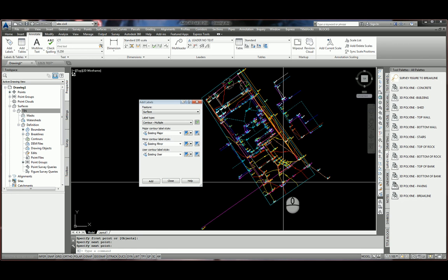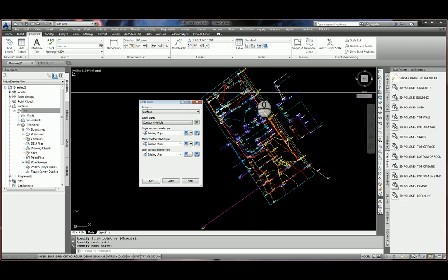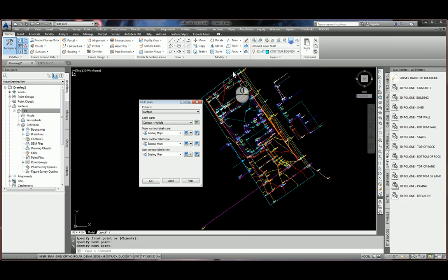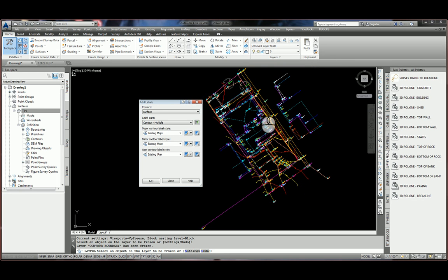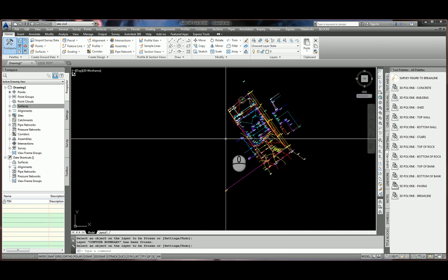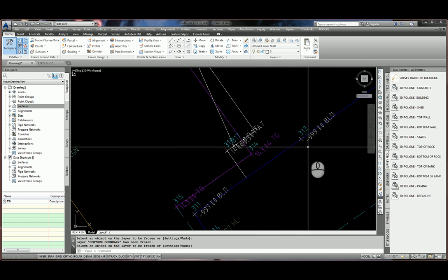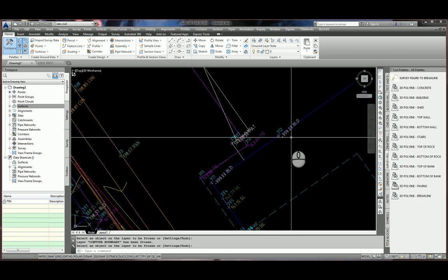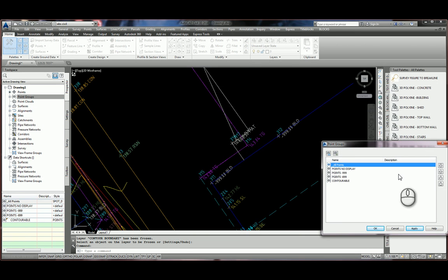we're now up to exporting it to ACAD. What we want to do is go home, freeze off that layer. It's the current layer, so change it onto 0. We'll freeze that layer. What we need to do now is change the hierarchy of the point group. I only want to show a code for the tree, and we don't want to show any codes whatsoever for the -999s. To do that, you go to the point group, go to properties, make sure all points is on the very bottom. You go apply and go OK.